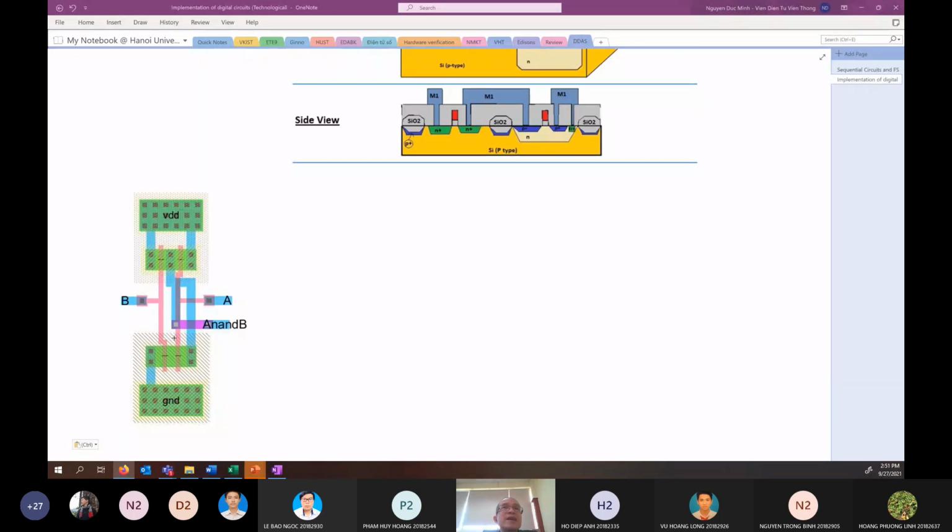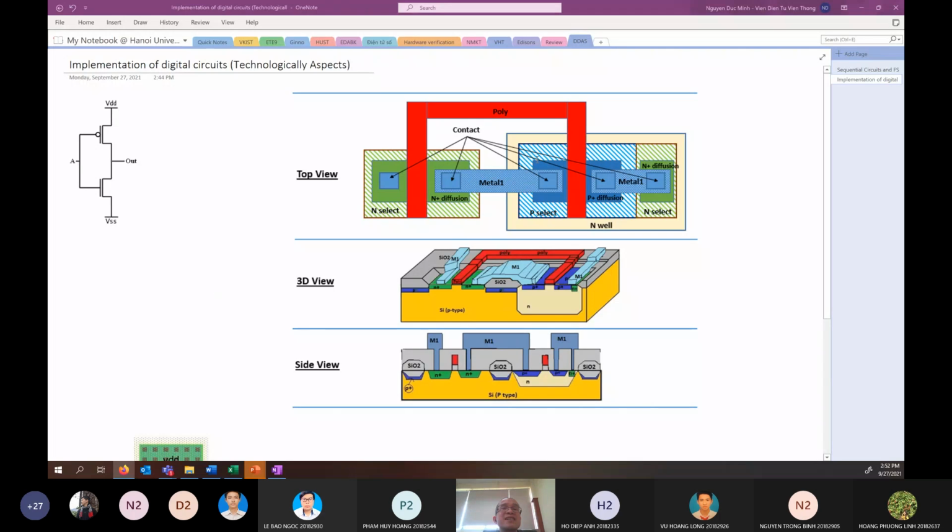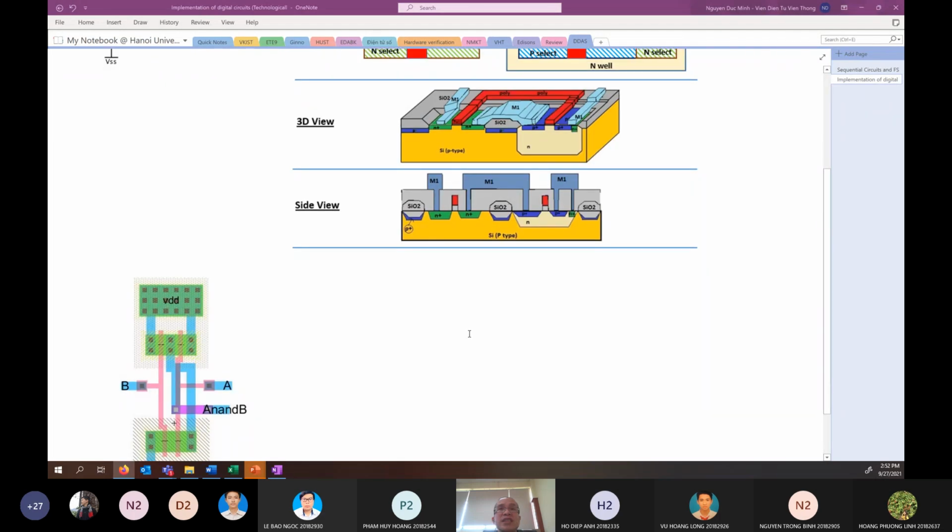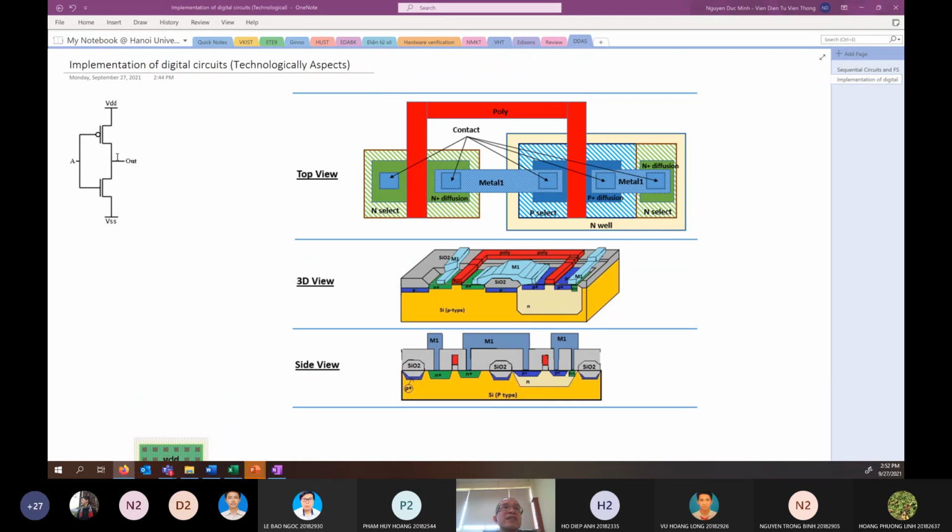It's ASIC. So that means in order to design an ASIC, you need to at first create the gate level. The gate level means connecting many simple logic blocks together. And from the gate level, you create the transistor level. And finally, you create the layout. And from the layout, you can fabricate the circuit. Depending on the way you create the gate level, the transistor level, and the layout level, you have different ways to design your ASIC. Got it?